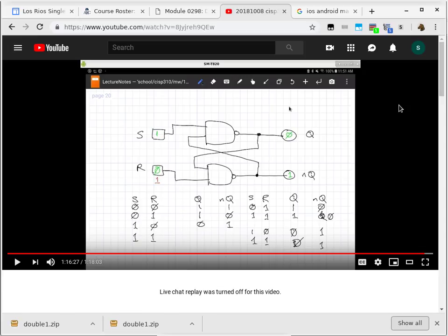And we'll keep doing that. It'll keep the oscillation basically forever. It won't stop. It will stop as soon as one of the inputs is a 1 and the other one is a 0. But it won't change any further unless the input would change. So this is the simplest memory device, called an SR latch.